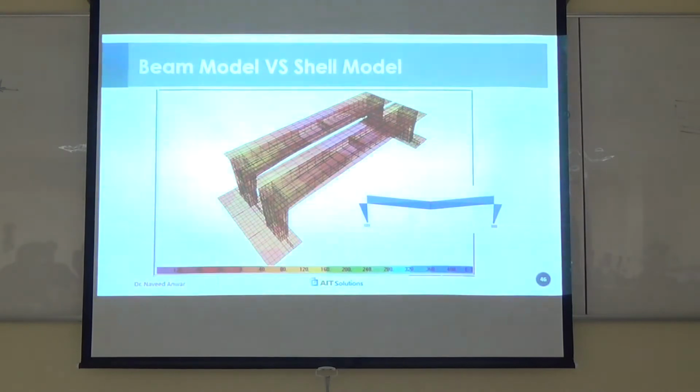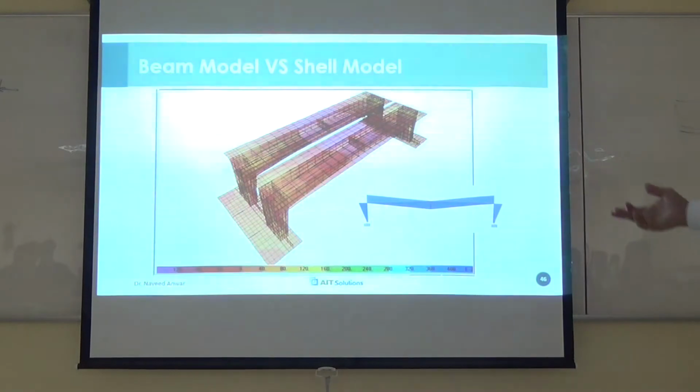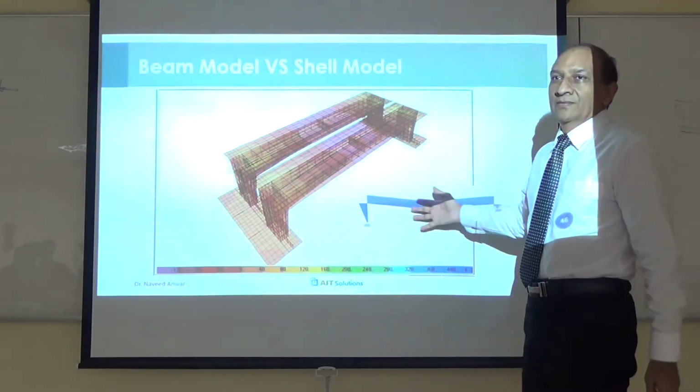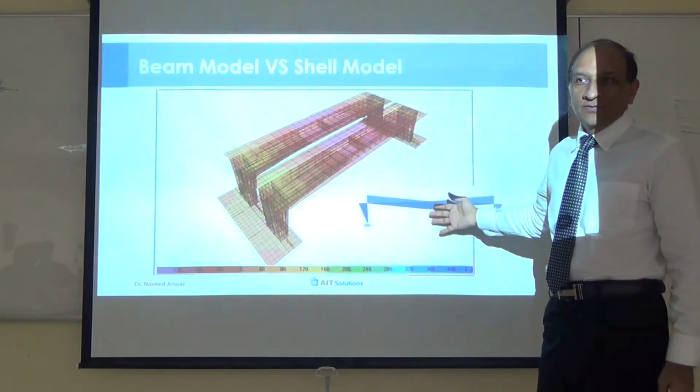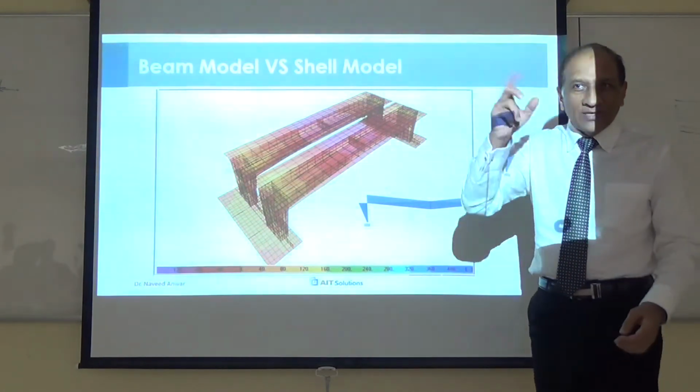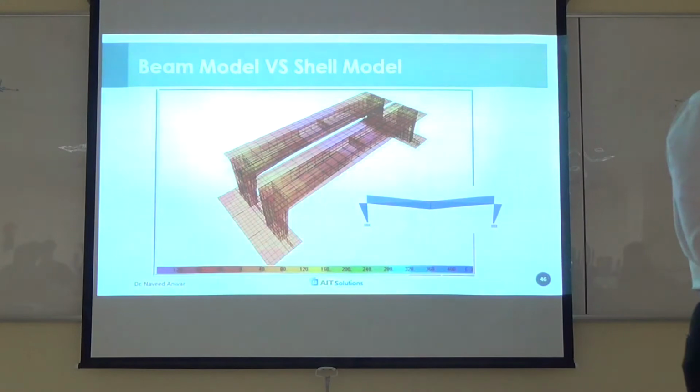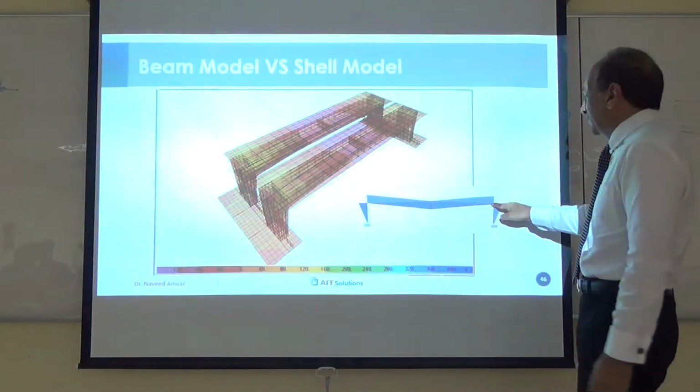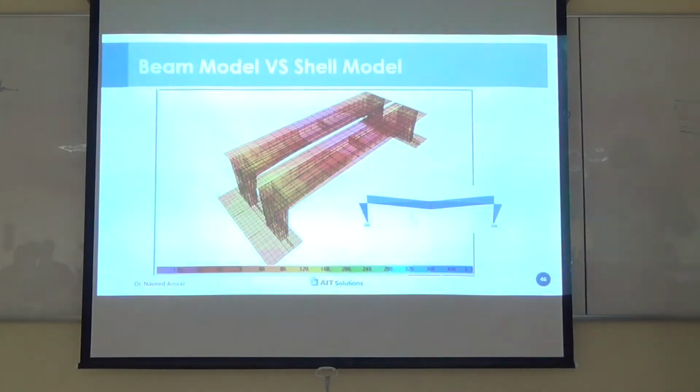So whenever you do complicated projects, we always recommend you make a complicated bridge model and a simple model with WL square by 8, always, to cross-check that the results are correct. Because in any bridge, this moment can still be calculated by WL square by 2 or WL square by 8, or whatever formula is right. So you can quickly check that approximately that should be the answer. And the bending moment in the column can also be checked by PL, PH over L. So all the calculations can roughly be done manually, and the final results should not be much different.